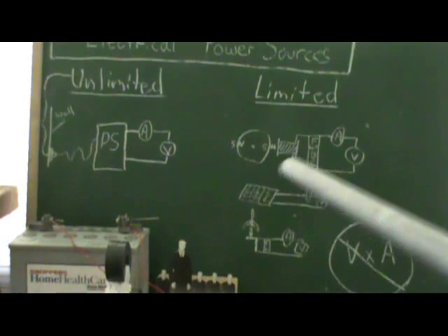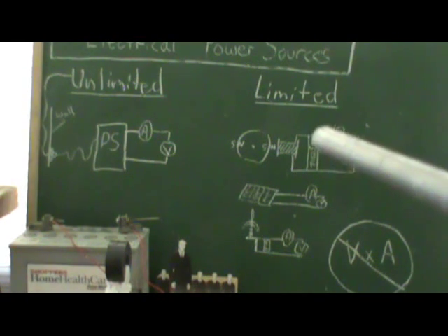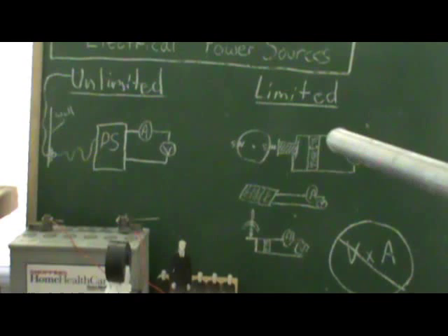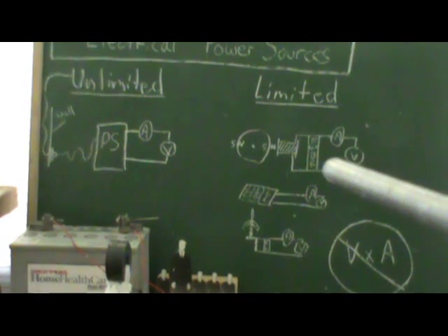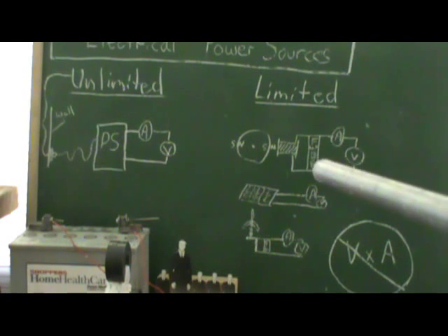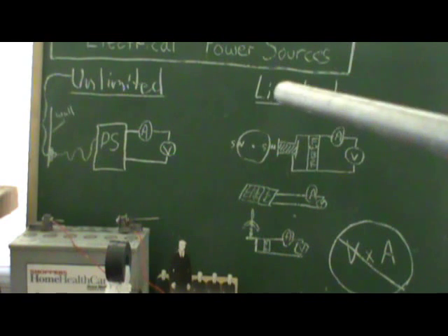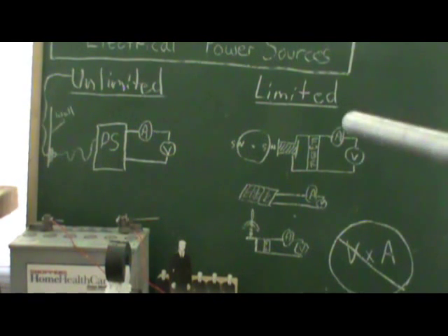But mainly what I want to point out in this video, the whole point of this video, finally getting to it, is that with a limited DC power source, so we have this full wave bridge rectifier here, that's what that thing says there, FWBR, going through this full wave bridge rectifier, measuring amps and volts and multiplying them together with a limited power source is not going to be accurate in most instances.